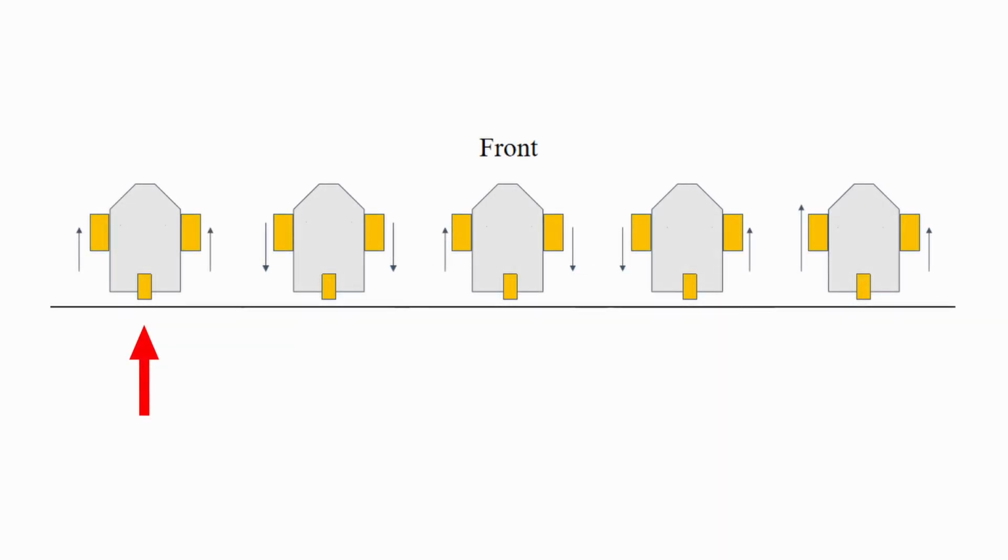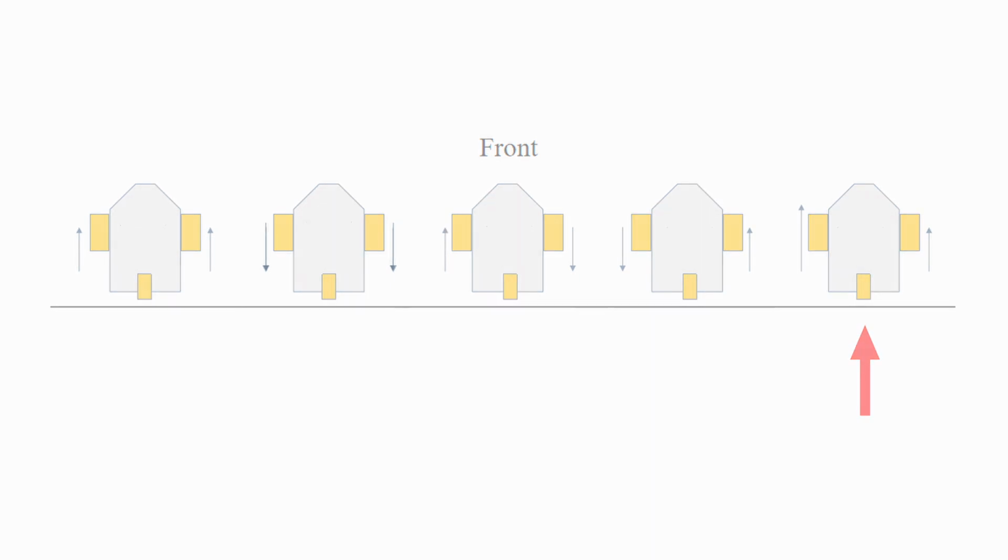When the left and right wheels rotate forward at the same speed, the car moves straight forward. When the left and right wheels rotate backward at the same speed, the car moves straight backward. When the left wheel moves forward and the right wheel moves backward, the car rotates clockwise. When the left wheel moves backward and the right wheel moves forward, the car rotates counterclockwise. When the speeds of the left and right wheels are different, the faster side determines the direction of turning and the radius of the curve, allowing the car to move in a curved path.